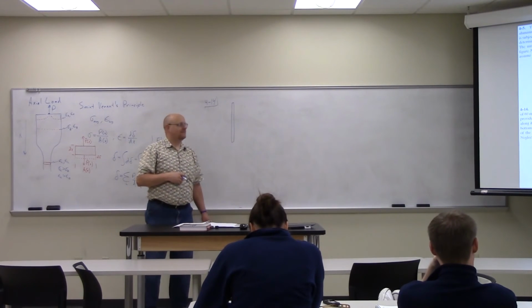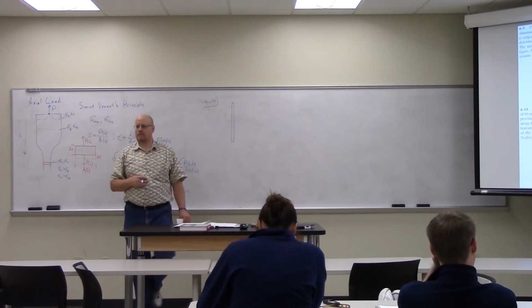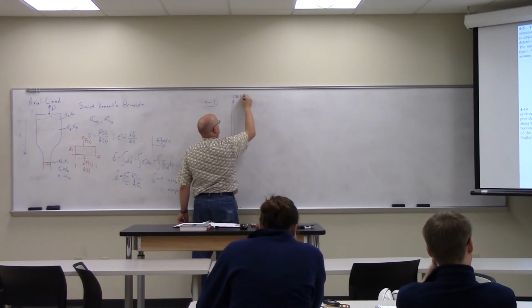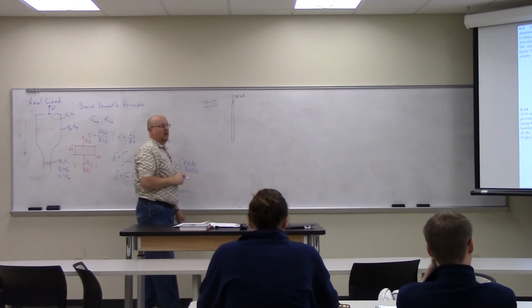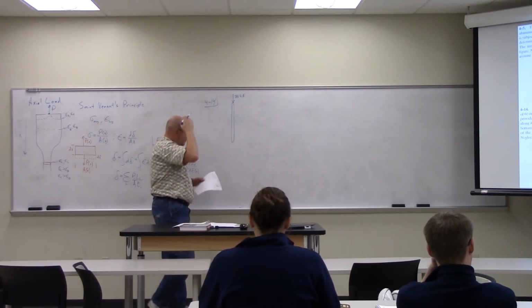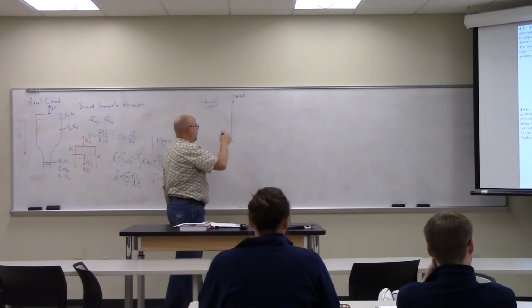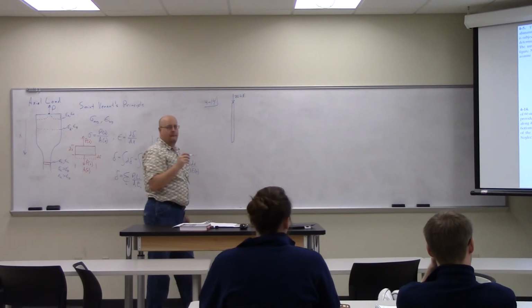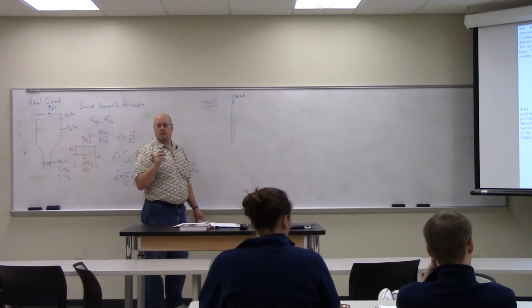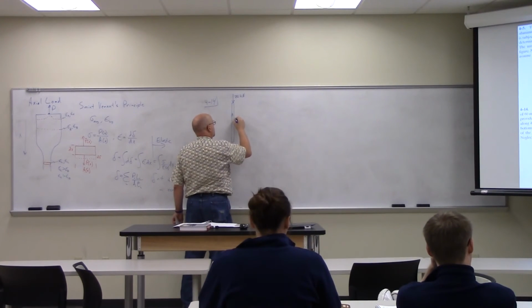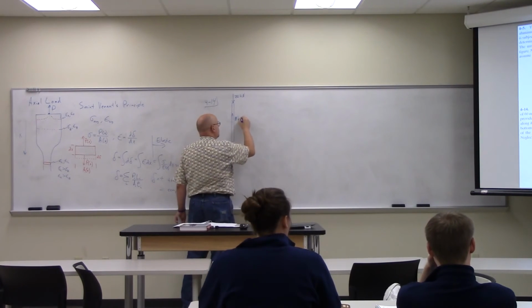What forces do I draw? We can start with the 20 kilonewtons. 20 kilonewtons pushing down. What else? The friction force going up. Where do I apply that force? It's applied evenly, so I guess you could apply it in the middle at 4 times 2. So that would be 8 kilonewtons.